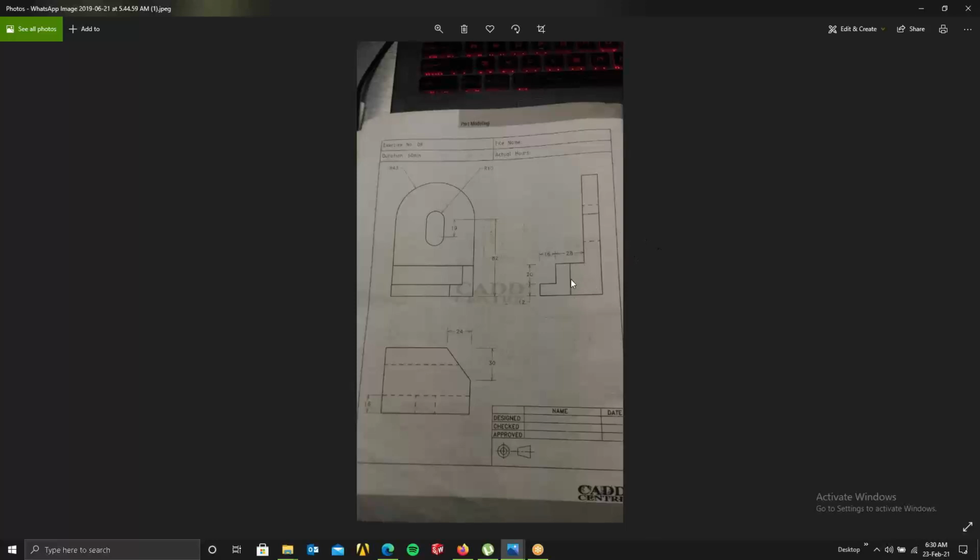Then you can draw this part and extrude it again. Or you can take your side plane, right side plane or left side plane, and draw this element like this and extrude it both ways. That's more convenient. If you select the top plane, first you have to draw this part, then draw this rectangle and extrude it 28, then draw this rectangle and extrude it 16. So it's three steps, three unnecessary steps you're taking here.